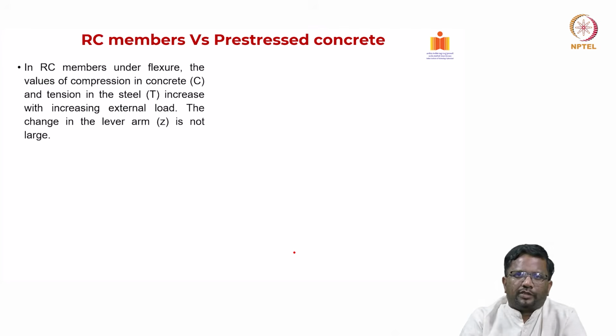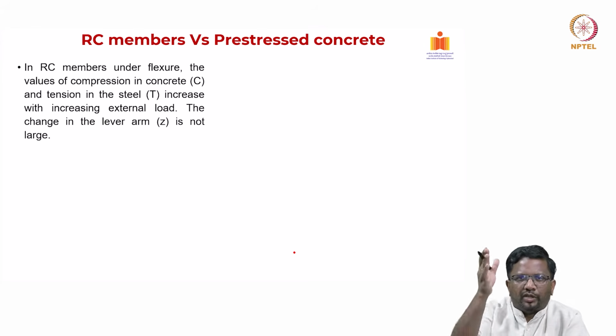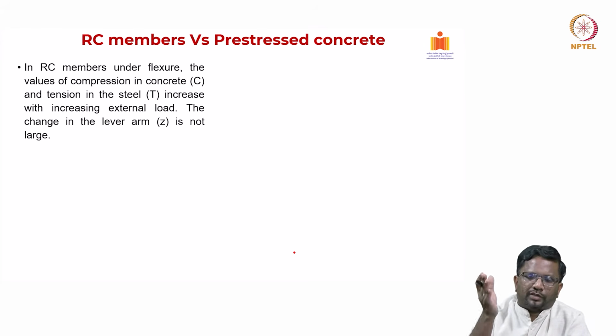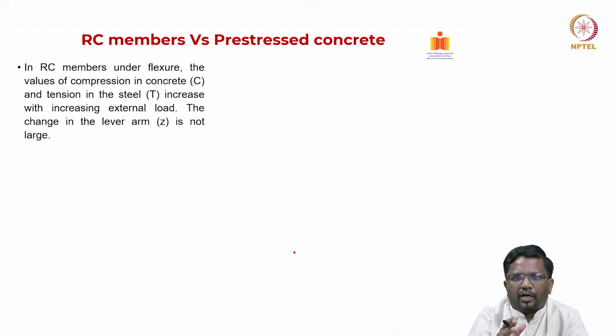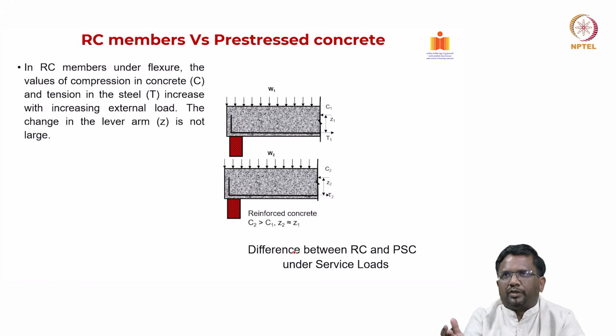Okay. Now let us see. When we do the analysis, this is your stress method of analysis. Now we can also do the analysis using the force method or C-line method. So before that, let us understand how the internal forces and resistance are changing under service loads between a reinforced concrete section and a pre-stressed section. So let us look at it.